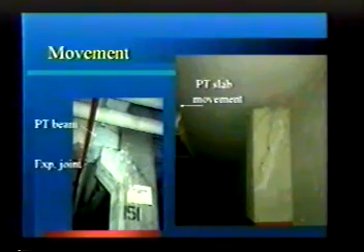This happens to be a post-tension structure. In this one, we have a large post-tension slab, concrete wall, and a very rigid column, and these huge cracks in the column. Well, why did that one crack? That's not a compression failure. In this one, the slab moved in this direction and pulled all the columns. Now, I only show one of the columns. It just so happened every single column was having that same crack pattern. That was over towards this end of the building. On this particular one, this was a slide bearing. It was an expansion joint.